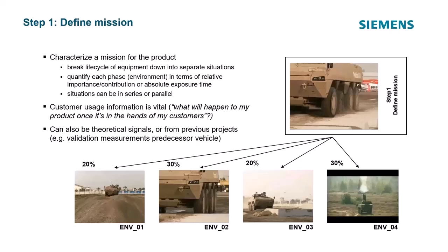If you already have a proving ground schedule, then this is a lot easier because you can take that proving ground schedule data and you can say, okay, how much do they run at track A, track B, track C, track D, however many they have, and then you can develop this profile. But if you're in a new market, this can be the hardest part. For the automotives, they have proving ground schedules they've had for years. So if you're going to put something on the car, they got a pretty good idea of what the loading profile is.